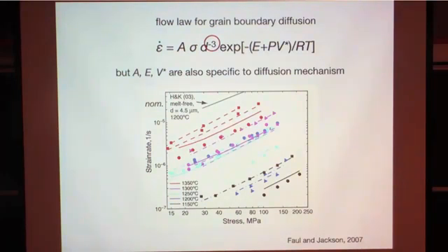And basically, right, so strain rates, time, I also have grain growth. So I can measure the grain size before the experiment, the grain size after the experiment. And this is the fit then to all of the data. I include the effect of grain growth, right? So grain size, because it's cubic, has a very strong effect on diffusion creep. So I need to include the effect of grain growth while I'm deforming. I'm not producing dislocations in this part. So while I'm deforming, I have grain growth, and I need to account for this increase in grain size in order to fit my data.